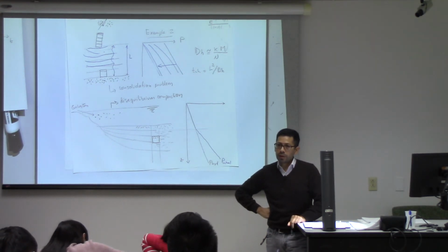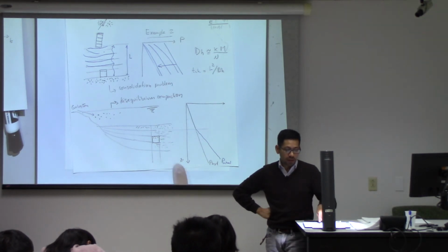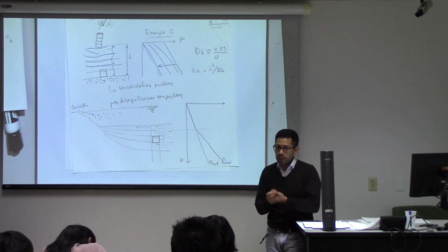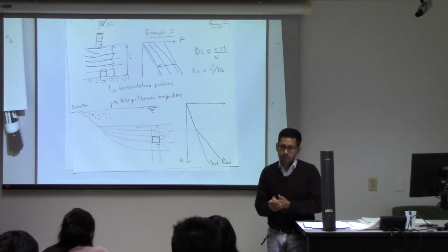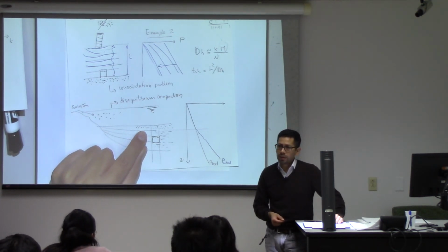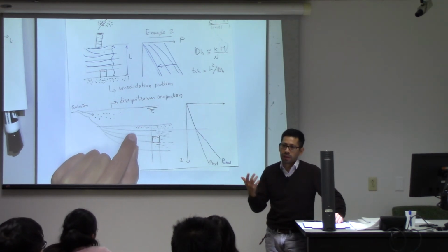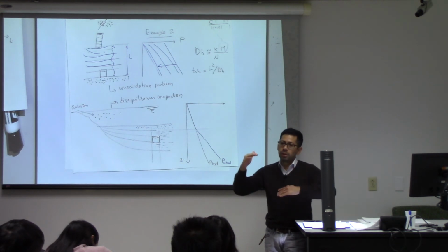So this is a problem in which there is still sort of undrained loading. The pore pressure is dissipating very slowly with time. And if you make some numbers considering viscosity of water, permeabilities in the order of microdarcy to nanodarcies, typical of clay sediments, you will see that for a 100 meters layer, it can take up to 100,000 years or 10,000 years for that pore pressure to dissipate.